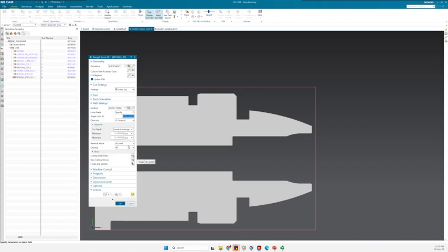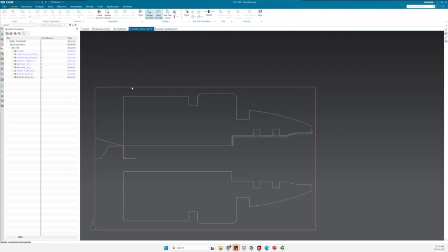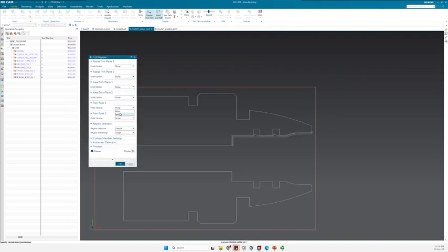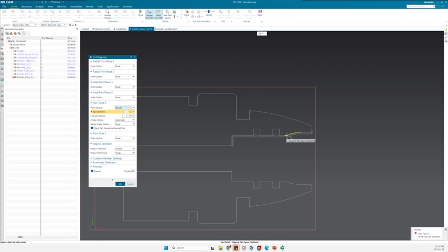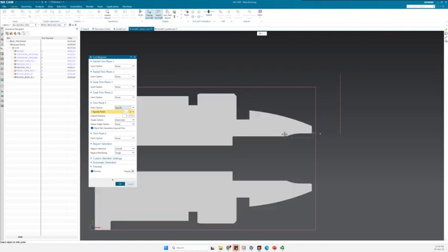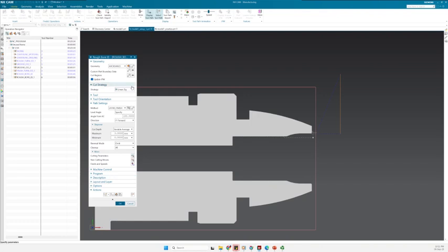I click this one. And then after that, of course, by the experience, we know that it's going to go toward the groove. So anyway, even if it might not be useful or not, anyway, we're going to have it omit here. Then I'm going to limit the cut region to the end of the curve. For example, I specify trim point 1 at the end of the curve so that I can just cover here. As I said, you have 1 for this one, for another element, and for the other one. So you need to define it one by one.